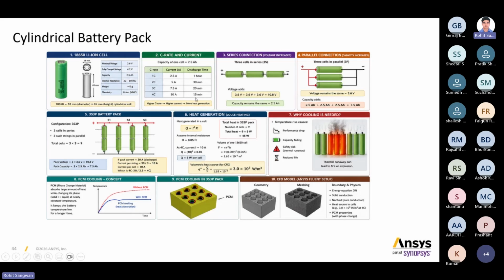So that's why you can see the charger you have at your home. 5 volt is also there, but you will see the ampere rating also, 25 ampere, 16 ampere. So for AC we keep 16 ampere switches. If I have a 2 ton AC or 1.5 ton AC and I'm keeping a normal switch MCB, it will melt and there will be sparking. The same way with the batteries also, because the battery stores energy and there is a phenomenon, electrochemistry.